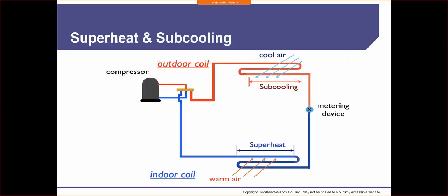So back to the same diagram that we had earlier. It's very similar. We've got the outdoor coil, and what's happening is it's going to remove all that heat because we've got cold air being blown across the coil. And you're going to say, well, cold air, it's 95 degrees. 95 degrees is actually much cooler than, say, the 120 degrees that the temperature is here.